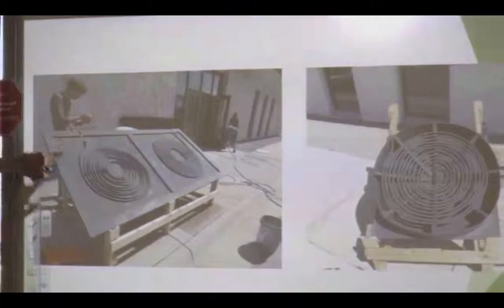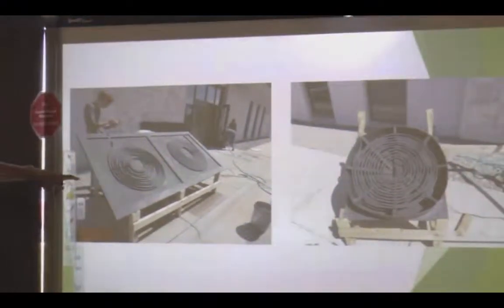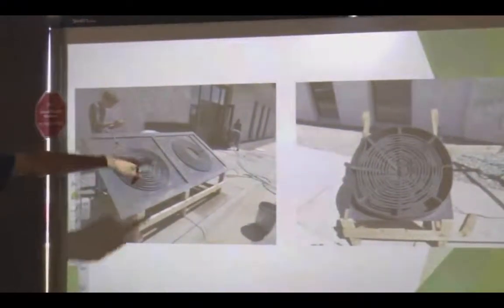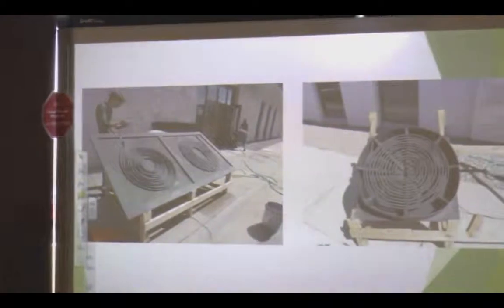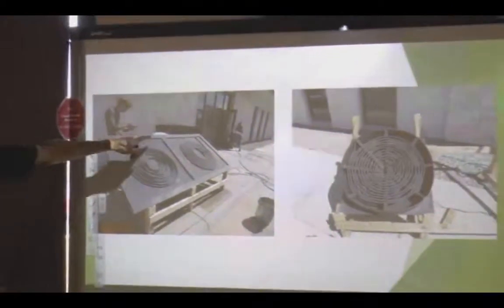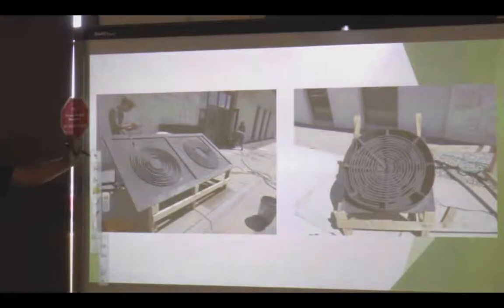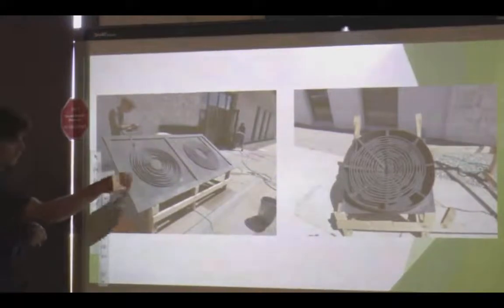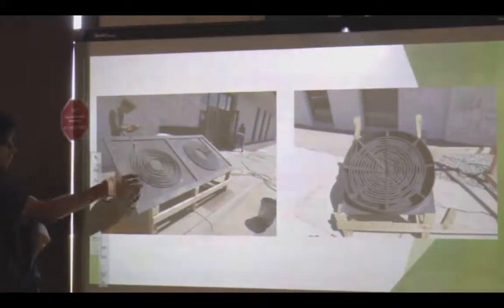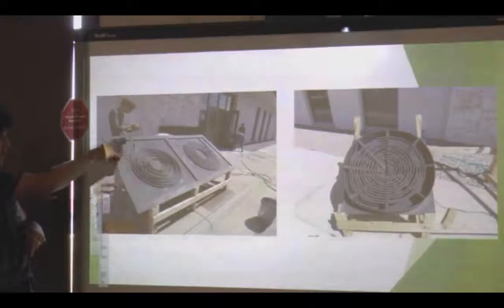This is the flat panel water heater. It's an 8x4 piece of 1/2 inch plywood with 1x4 sidings along the side. This left side is copper piping, 50 feet of 1/2 inch diameter copper piping. You can't see it from the side, but behind this there are 2 5-gallon buckets full of water.